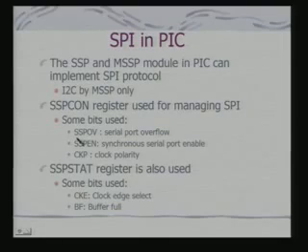If there is a buffer overflow, then in a shift register connection, data is flowing from master to slave and back to the master, but I have to store the data in a shift register. If that shift register is not getting cleared, there will be an overflow. So, the system should have an ability to detect whether such an overflow is occurring or not.